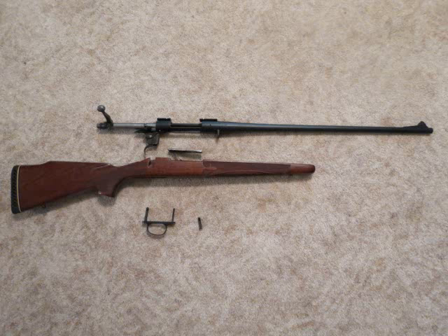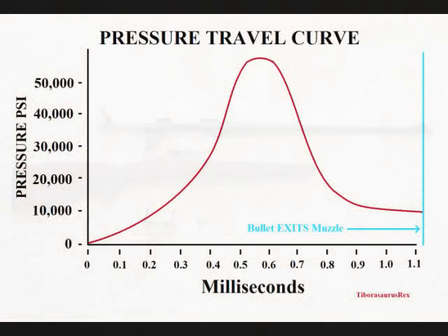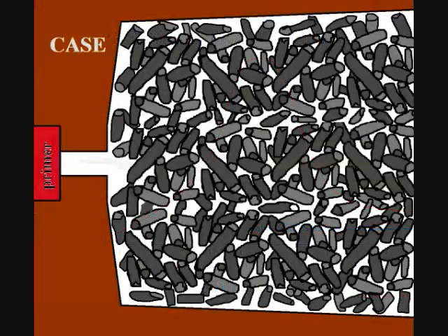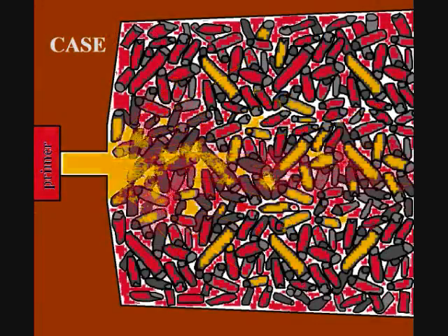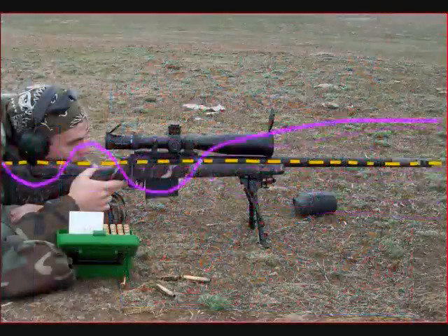And sometimes there's just a tiny minor variation in the ammunition or how the ammunition was laid in the chamber or the burn rate of the powder, but it changes your pressure curve, and that can change the harmonic nature of exactly where the antinodes and nodes are vibrating along your barrel.